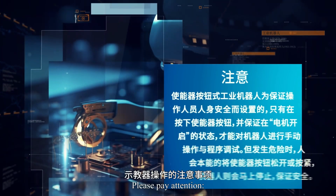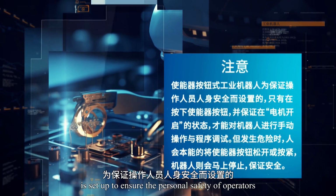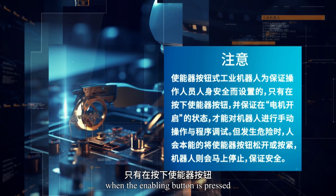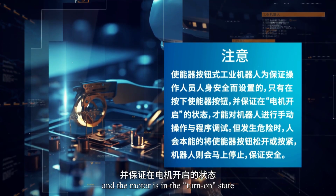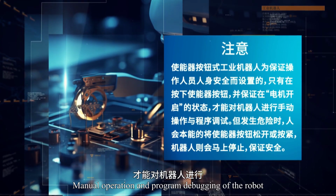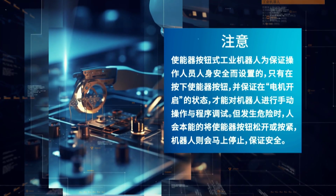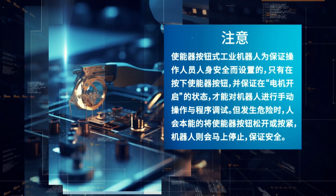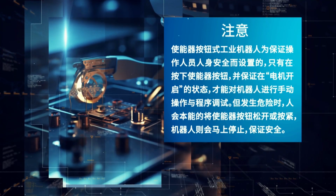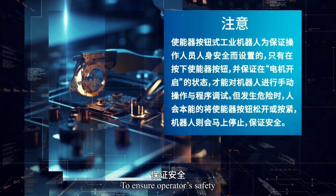Please pay attention. The industrial robot with the enabler is set up to ensure the personal safety of operators. When the enabling button is pressed and the motor is in the turn-on state, manual operation and program debugging of the robot can only be carried out. But when danger occurs, people instinctively release or press the button of the enabler, and the robots will immediately stop to ensure operators' safety.